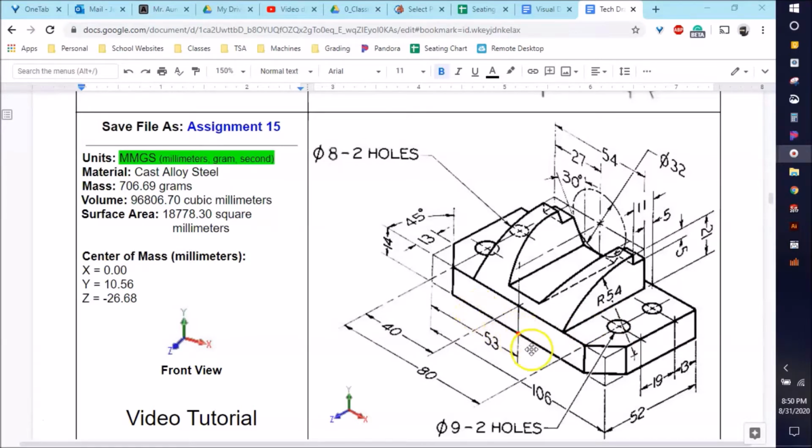and you can see that it is located on the bottom of the part, and it's pretty much right in the middle. You can also tell that just by looking at the overall width and the measurement that they give you from the far left side to the origin, and that is half of the overall width. So that tells me that this thing is dead center right on the bottom. Okay, and it's also on the front of this.